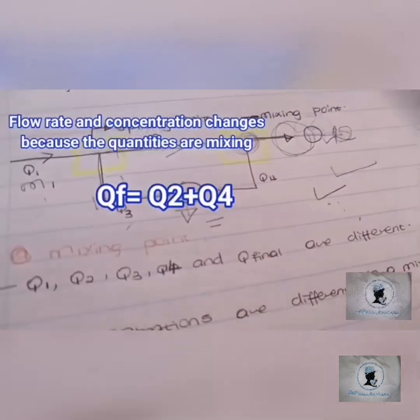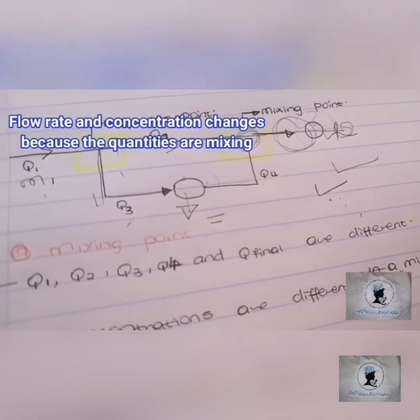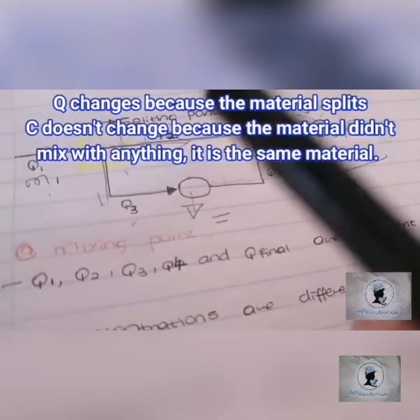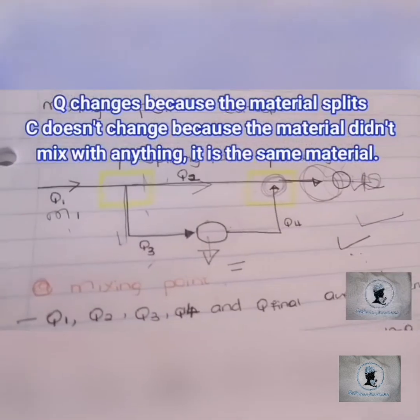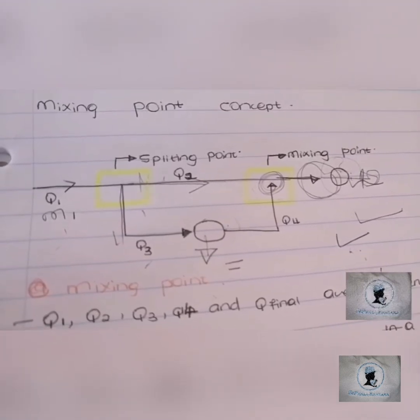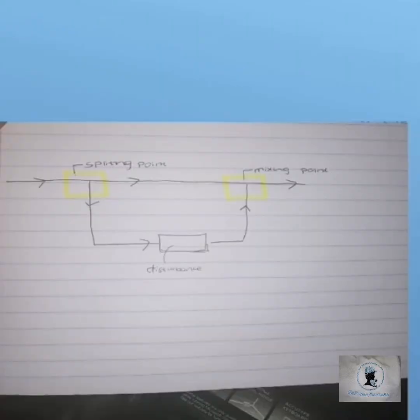And then also the concentration changes, the Q final, unlike when it's at the splitting point. At the splitting point, only the flow rate changes, but the concentration remains the same. So here with this diagram, the main reason for me to do this one was to explain the splitting point and the mixing point.